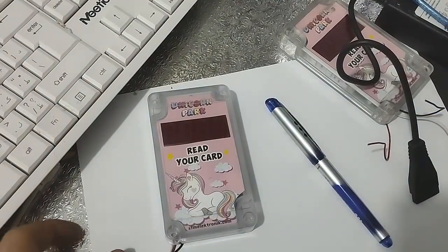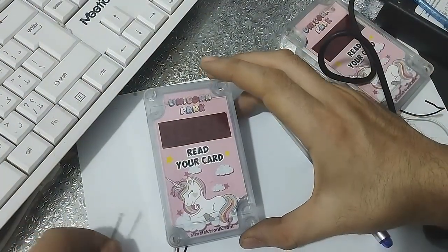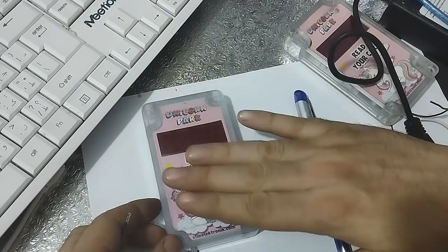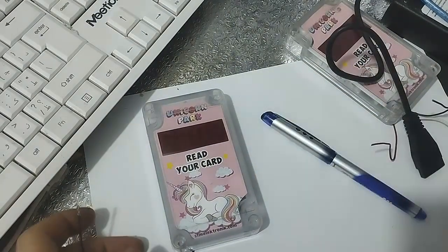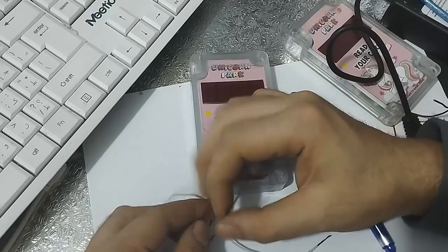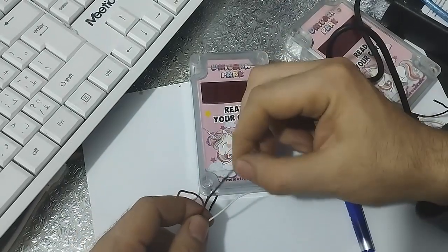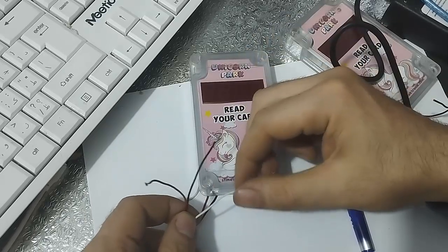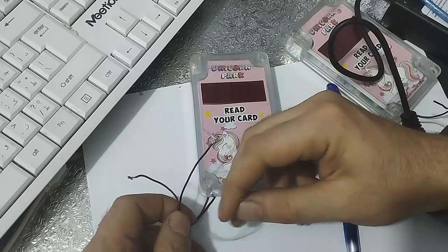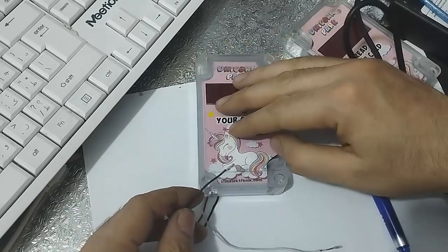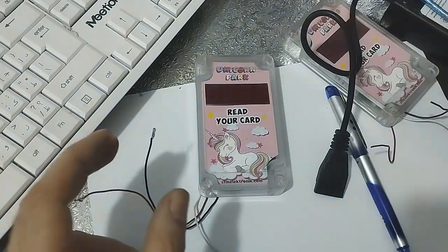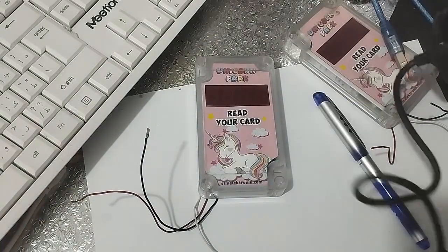First we will talk about the card reader. It works the same way. This is an example. I take it; the player has a card and puts it in. We have three lines: red and black for the DC voltage, 5 volt. Red is plus, ground is black, and the signal is on the white cable. Usually the white cable has 5 volt.